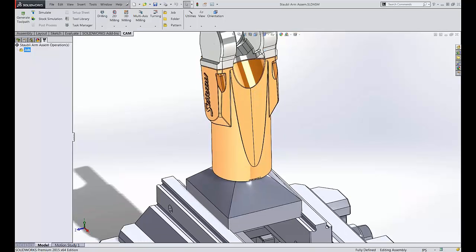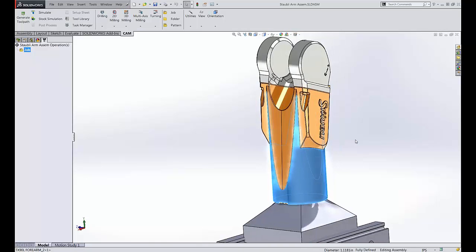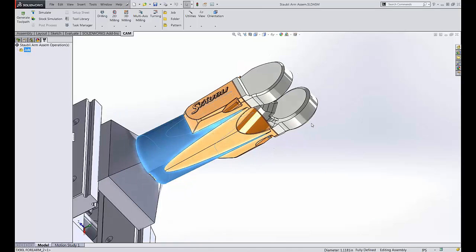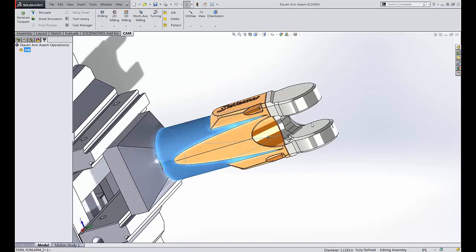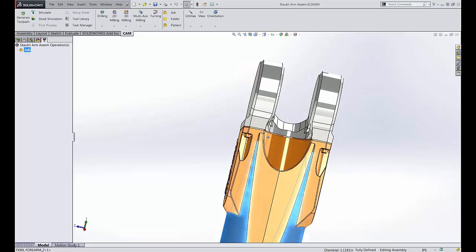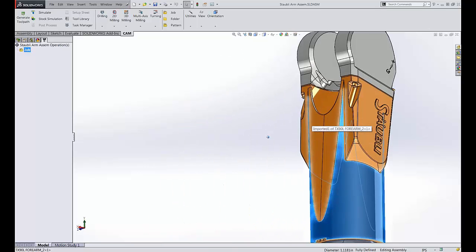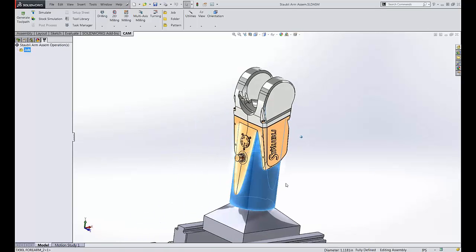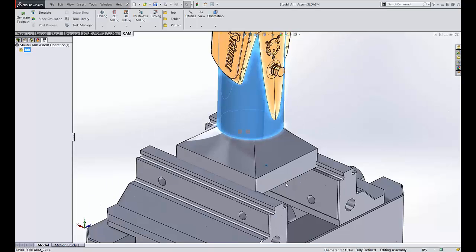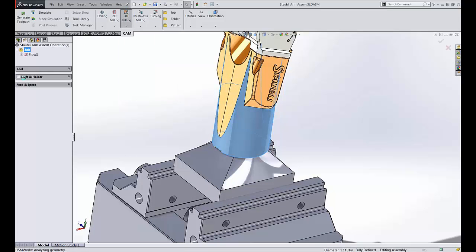Gotcha. I think this is probably the clear surface of where multi-axis would be a winner here. I think most everything else is probably 3+2 capable, maybe with some advantage to some 5-axis stuff in some places. This is probably starting to get to where you'd maybe want to use a tool that's tilted. Maintaining some tilt on some of these clean surfaces would probably be a good idea. But this one here, you just can't really do that any other way. It's occluded from the top. Any orientation, can't see the whole surface, but it's going to be a great candidate for Flow.